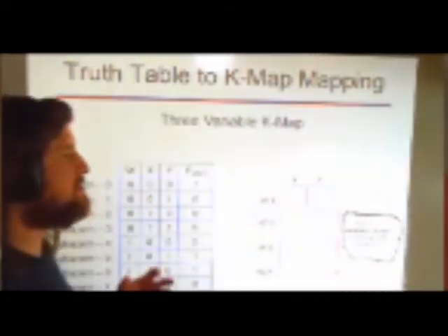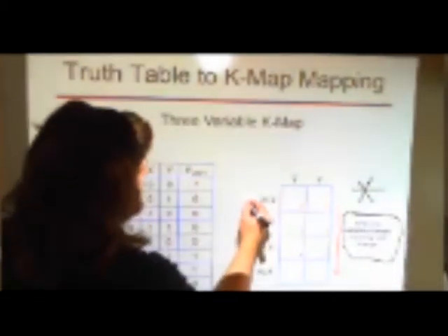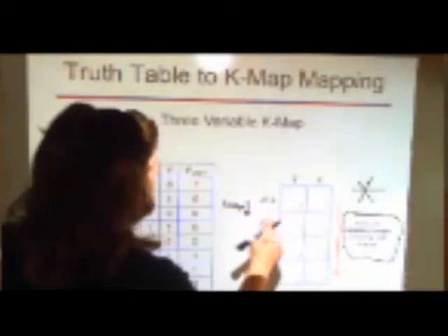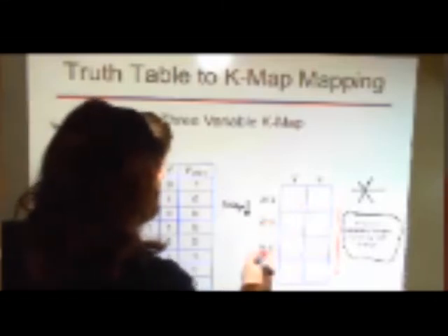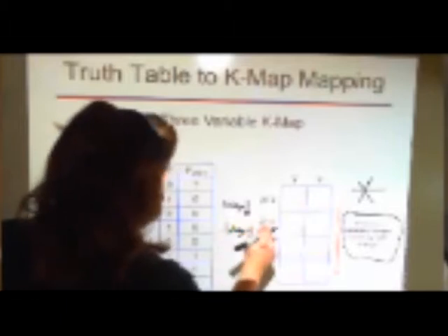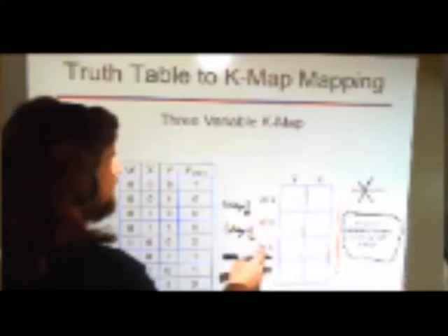If you are taking notes on your own, like in a red text or something, put a star, or if you have the notes, put a star by that section and an arrow towards that. Only 1 variable can change every time the row changes. And what that means right here, this is one change. When we go from W naught X naught to W naught X, only one thing changed. When I go from W naught X naught to WX, it's only one thing changing, right? We went from having W naught X to WX, right? Only the W changed there, not both of them.